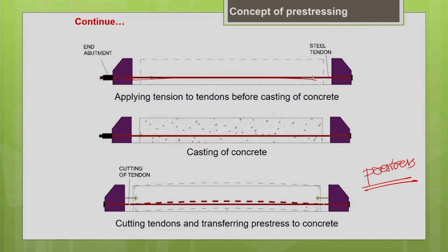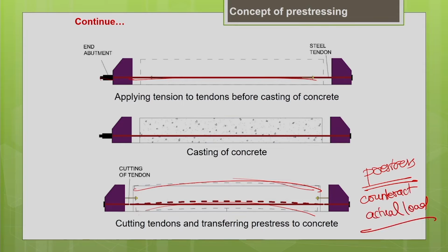You can see how it is subjected to stressing. So what happens is when it is subjected to the actual load, this pre-stress developed will counteract the actual load. That is why your load bearing capacity will increase, as well as these piles cannot undergo deflection easily, and the handling will be easier. It is not easily subjected to handling stresses. It can easily take the handling stresses. It is not susceptible to damage during handling. So that is the main advantage of pre-stressed concrete pile.